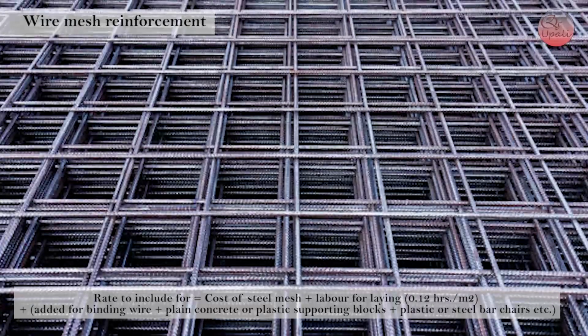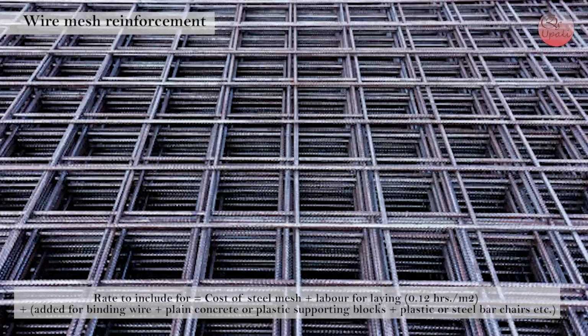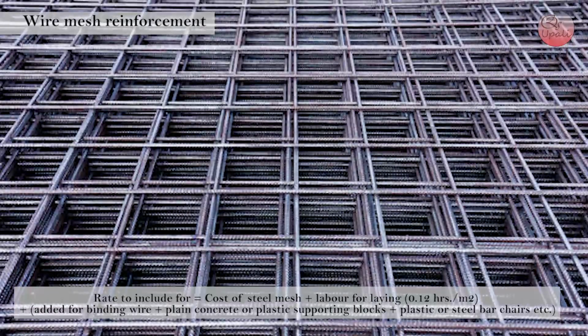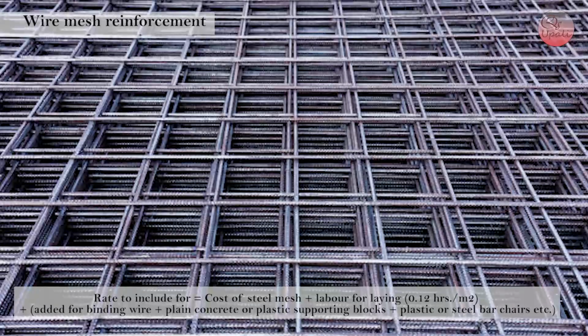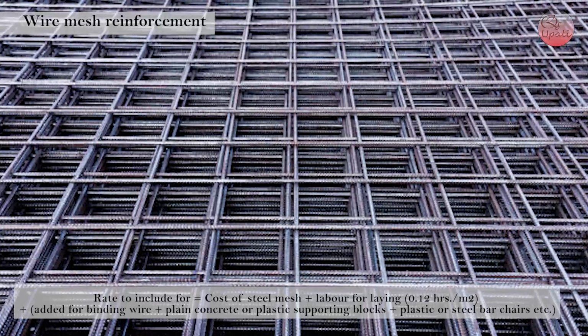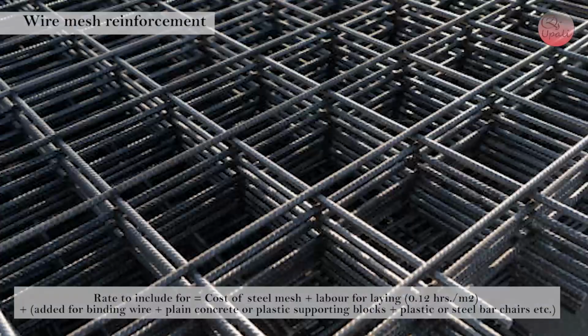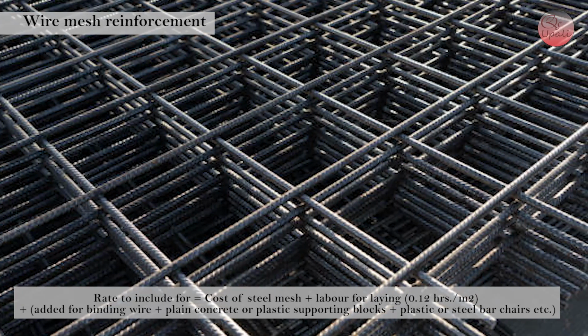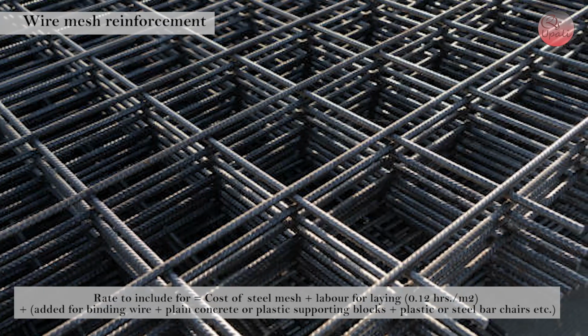Wire mesh reinforcement. Rate to include: cost of steel mesh, plus labor for laying at 0.12 hours per meter square, plus binding wire, plus plain concrete or plastic supporting blocks, plus plastic or steel chairs etc.